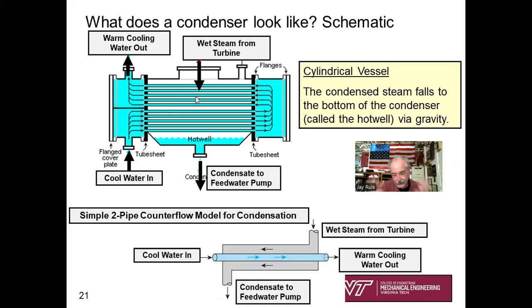We've got to condense that steam somehow, and we do so using a low temperature heat source in these blue tubes. A little bit more on that in a minute. These blue tubes, I wouldn't say they're cold. They're probably about at room temperature. Whatever's in those tubes would be sort of room temperature water, and that is plenty cool enough to condense that steam.